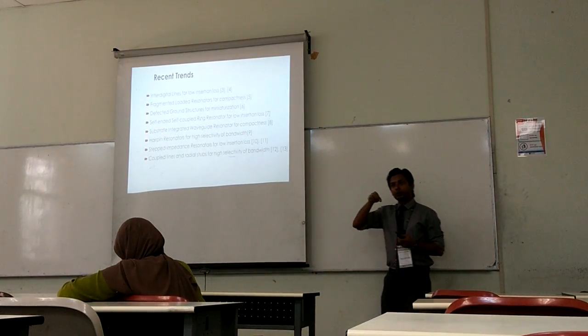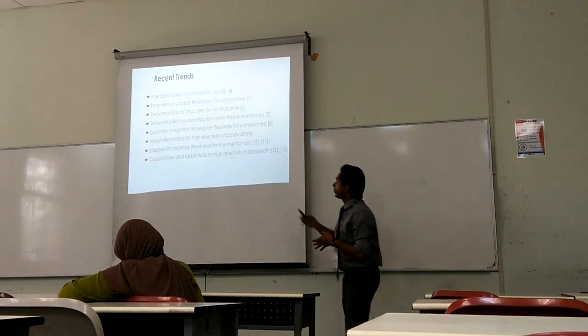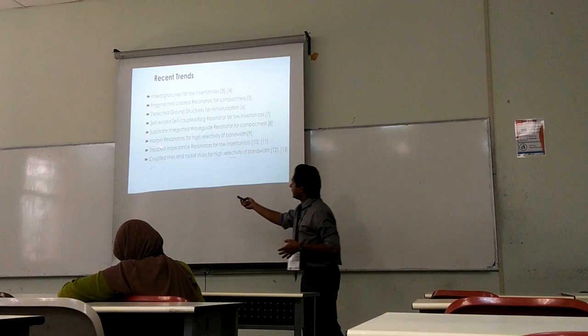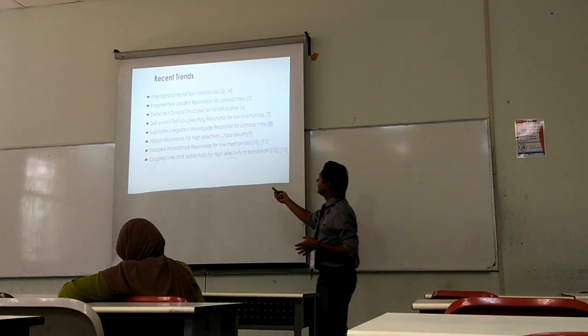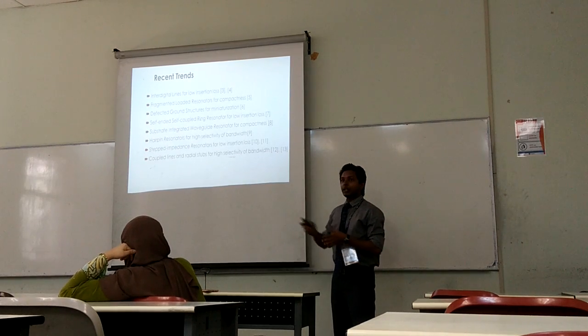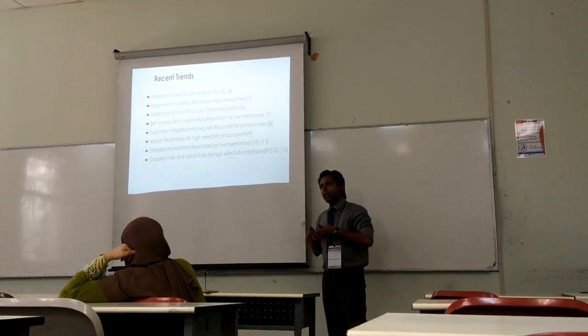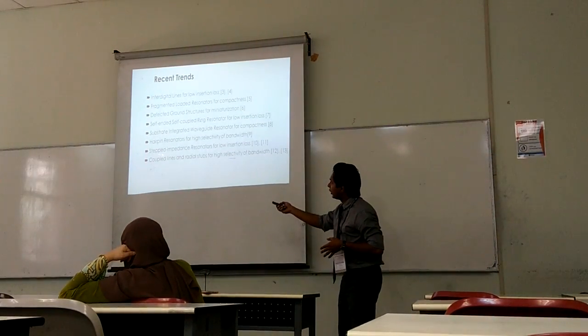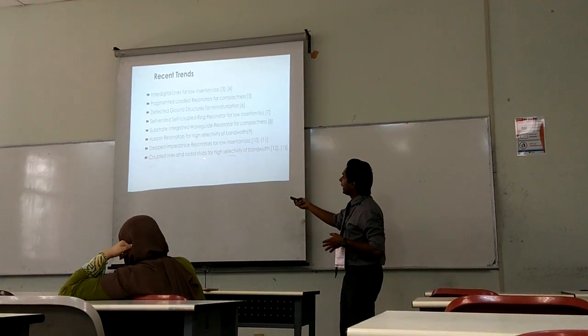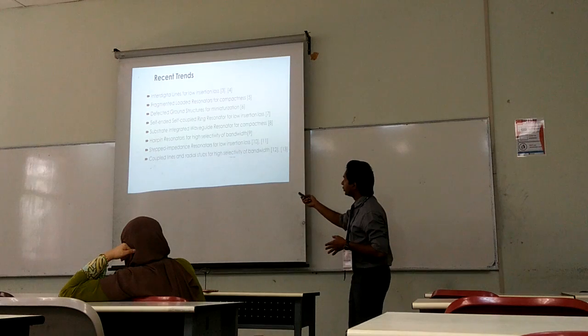It's interesting that you use some holes for substrate integrated waveguide. It's also for compactness. This is the hairpin resonator for high selectivity. It's interesting that the hairpin resonator can sharply select your band. This is one of the good features of this. Also, step impedance resonator, coupled line, and radial styles for high selectivity and insertion loss.